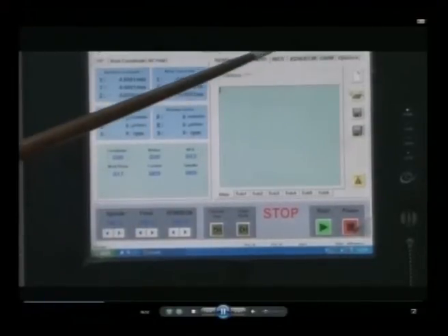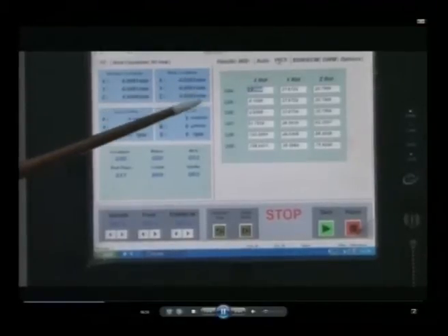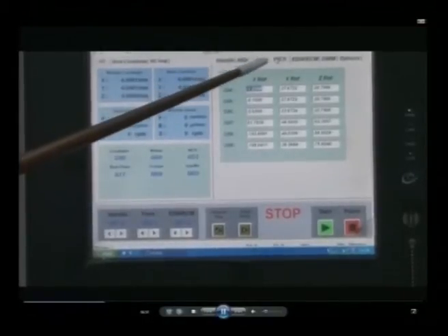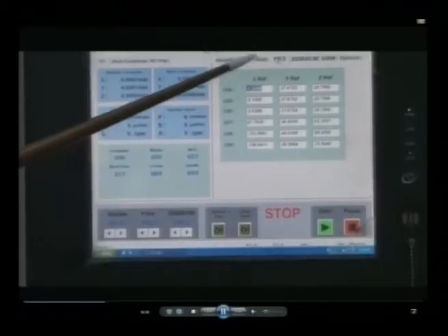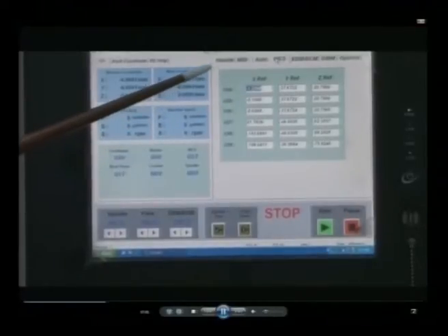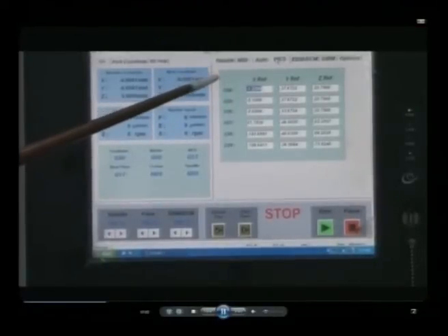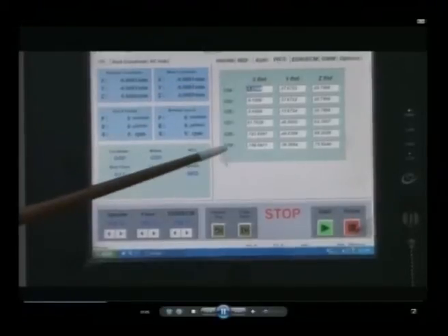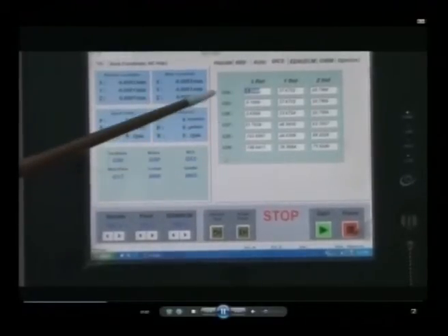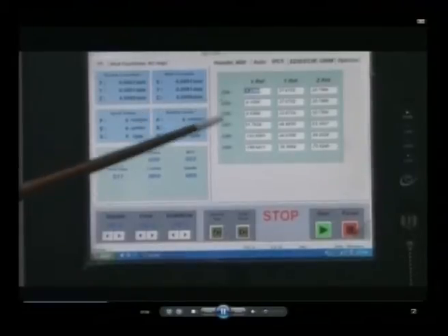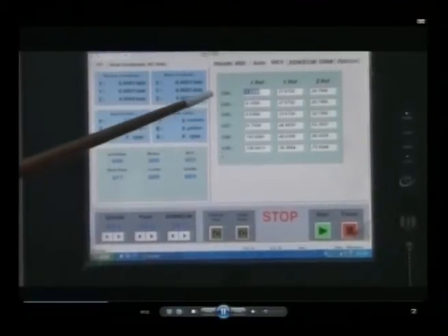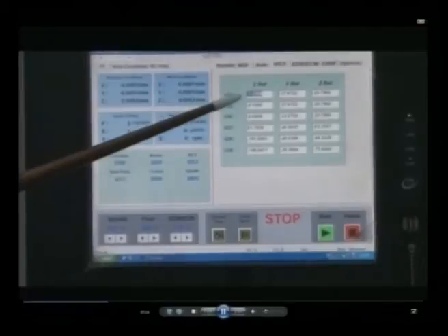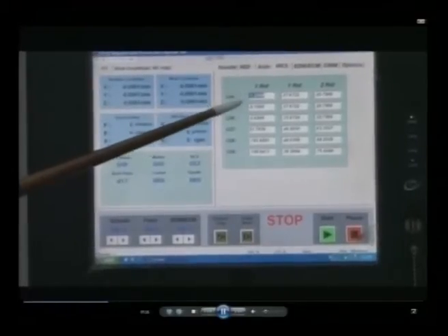The next window is WCS. WCS refers to World Coordinate System. In this machine, there is a feasibility for having 6 different origins on the workpiece. So the origins can be G54 to G59. Each G code will have a corresponding point, which is called P1.